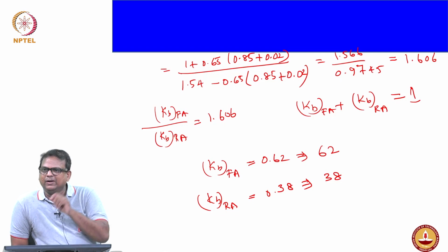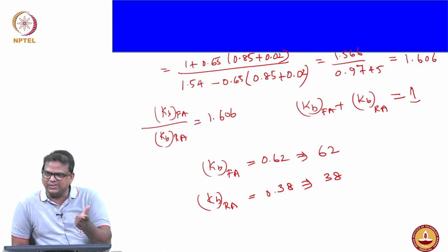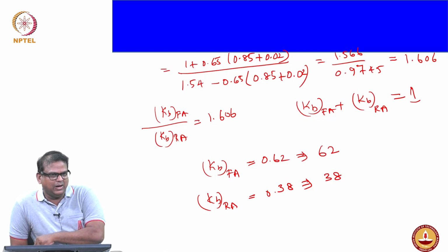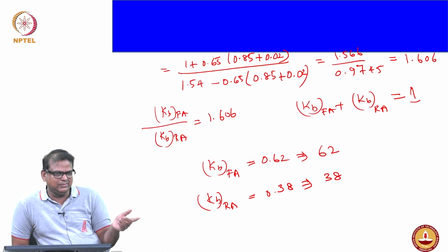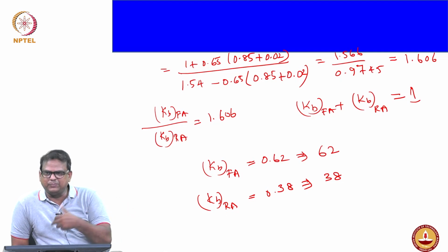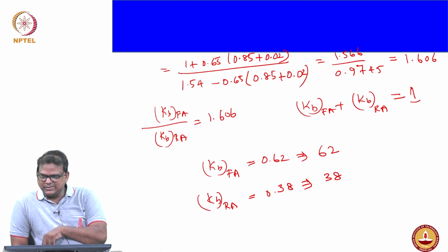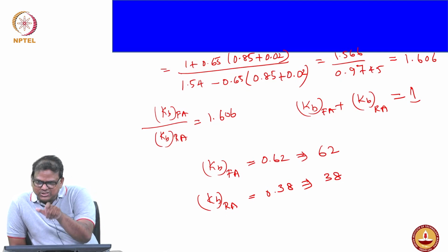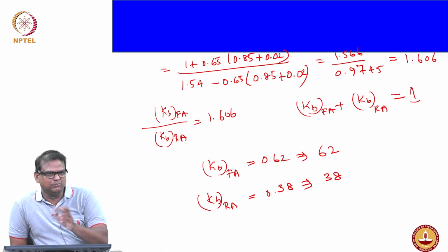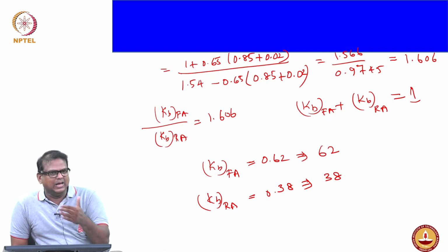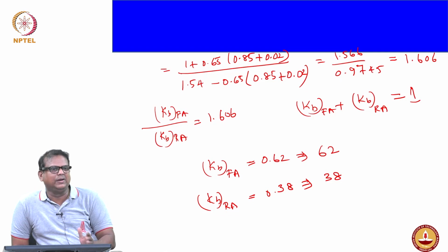They are asking about using the same braking proportion if mu s is changed. Ultimately, what we want to understand is, if you have the same road adhesion and change the brake distribution, what will happen, or if you have the same distribution but change the road adhesion factor. Both ways we are trying to understand that. That will give us the critical role of the distribution as well as the road adhesion factor, or coefficient of road adhesion mu s.